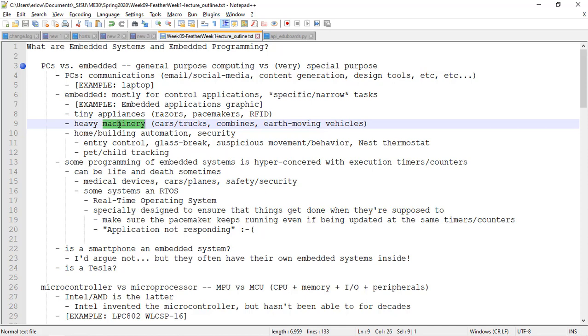Maybe it also sets a timer that if it doesn't hear a heartbeat within three quarters of a second, then that in and of itself is an event, right? It's a timer saying, hey, listen, I didn't hear a heartbeat well within the amount of time that I should have gotten another heartbeat. I need to kick in and do something. So in some respects, some events can actually be self-generated. Setting yourself a timer for some point in the future is of itself an event. It's not an external event, but it's an internally generated event. Without it, you can't really implement a program to perform the function that it's being asked.